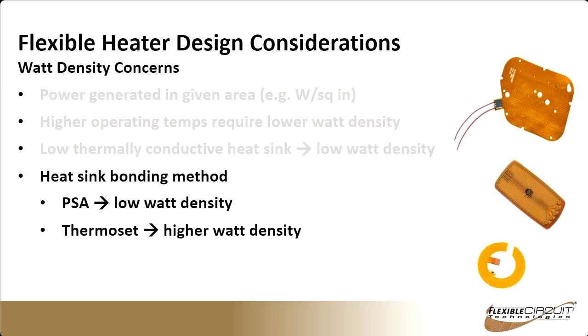And Chris went over the bonding method a little bit. PSA probably makes up 80 to 90% of what we do. A lot of customers like to be able to install the heaters themselves, and it is a very effective way of doing it. You can get good heat transfer. There will not be a void-free lamination.